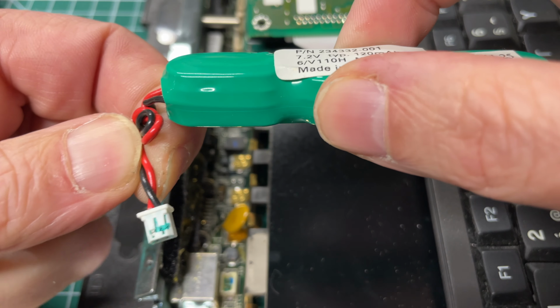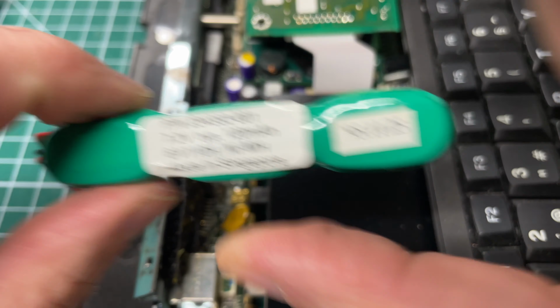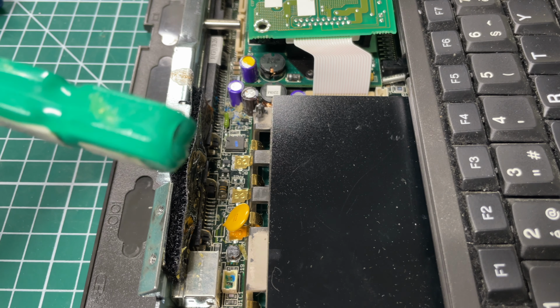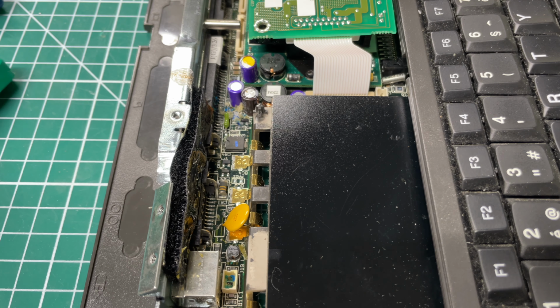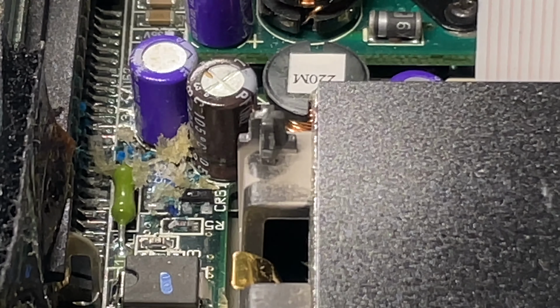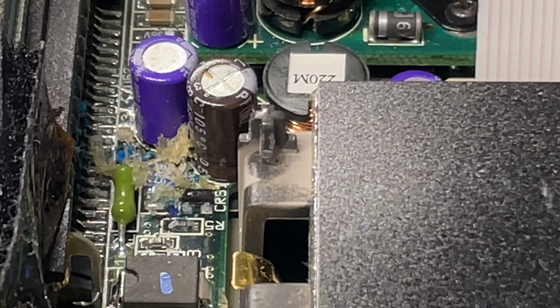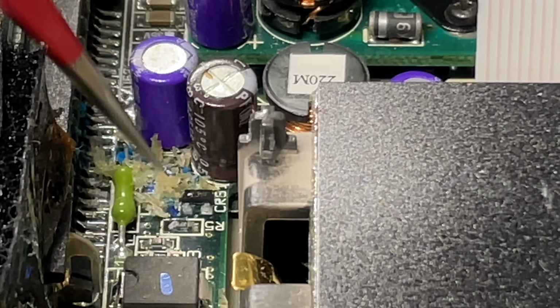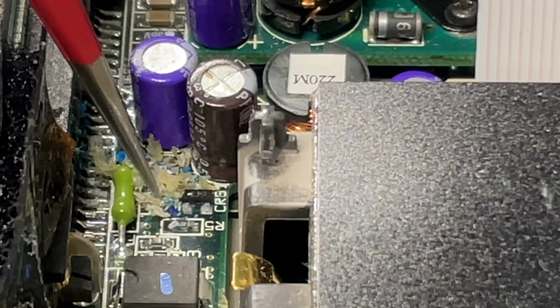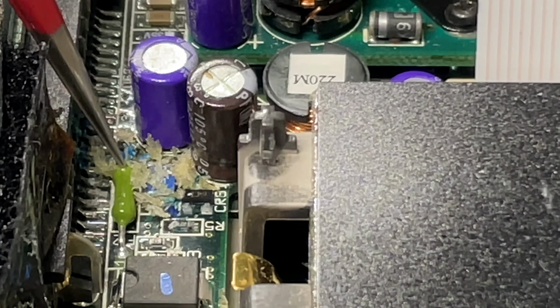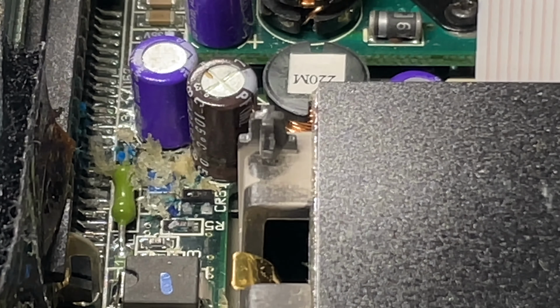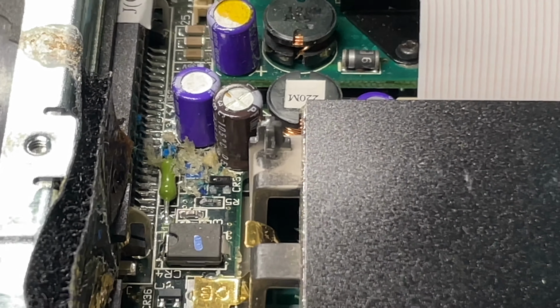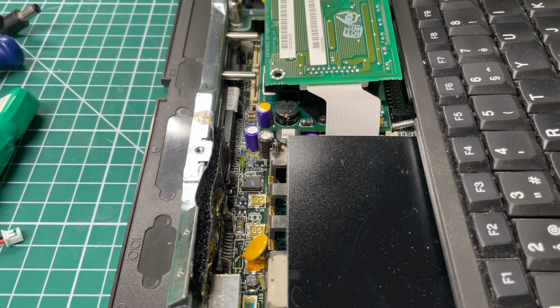So yeah, there's definitely some leakage here, as you can see in the connector, but it's not too bad. So I don't think it caused that much damage on the motherboard. I did notice here around these capacitors that there was this dried up stuff. I think this is dried up glue. I don't think that these capacitors have started leaking. But yeah, you definitely can't rule out that these capacitors might have gone bad. It's not just because you don't see something visually that the capacitors might not be in need of replacement.